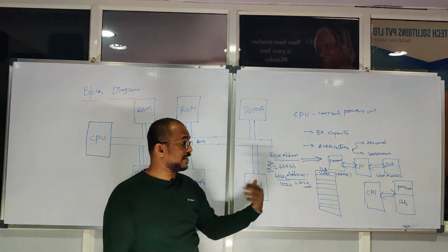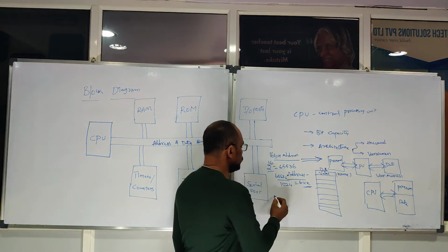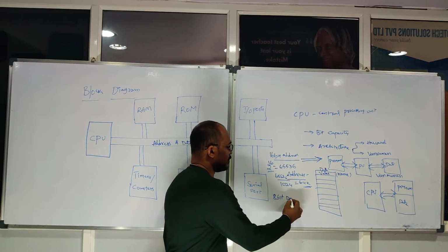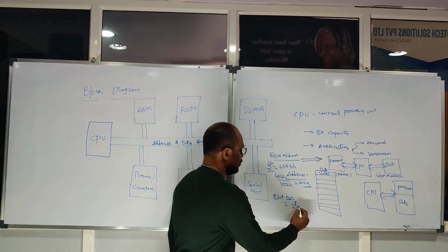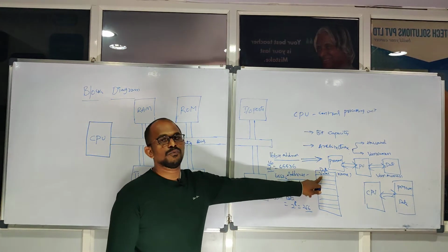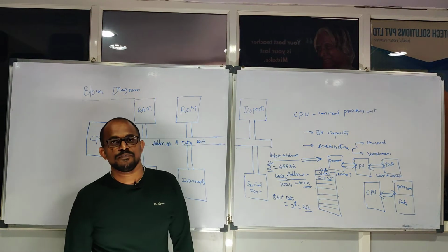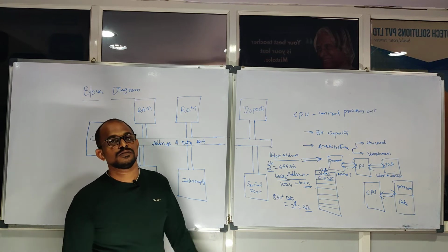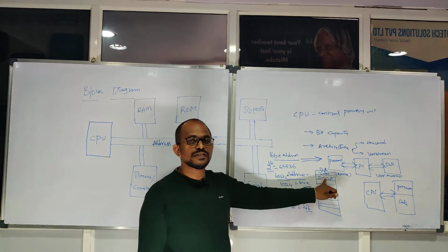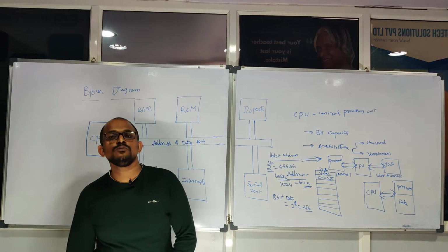And what does the data bus size decide? The data bus size decides the maximum value. Suppose the controller has an 8-bit data bus. This 8-bit data bus decides the maximum value of 256, the amount of value I can keep in one location, which is 0 to 255 only. Suppose your input is 1000, so you need to use 2 memory locations to save it. If the value is less than 255, the device will utilize only 1 memory location. If your input is more than 255, you need to use 2 memory cells.